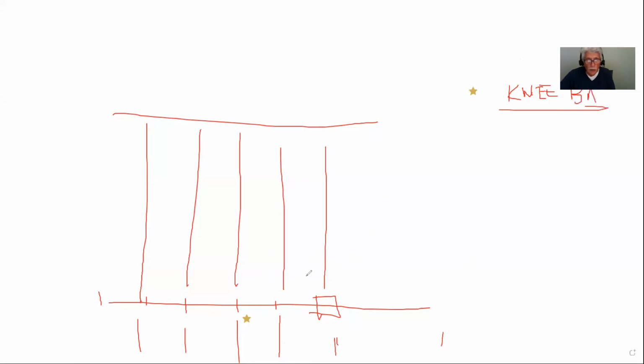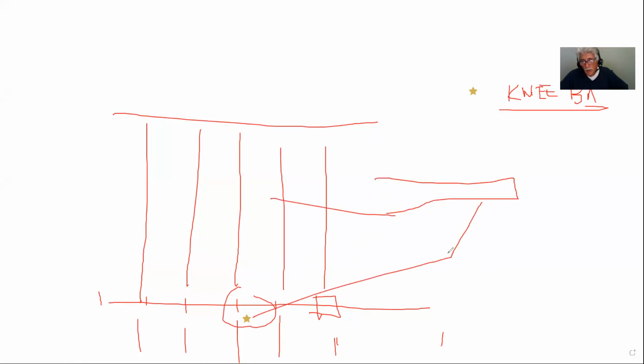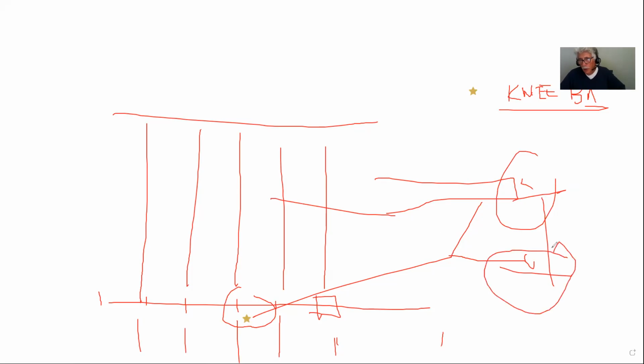By putting knee brace, the manufacturer of the joist knows that when he designs his joist, he's going to provide a member that will laterally support the girder that is supporting the joist. And by putting a knee brace there, I'm going to be laterally supporting the compression part of that flange that has a negative moment. Is that a little clearer?